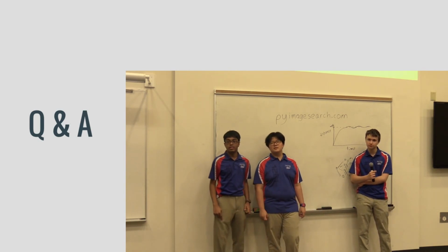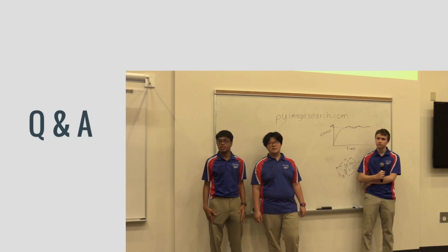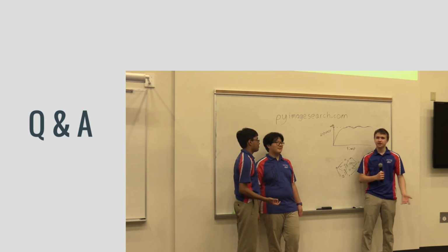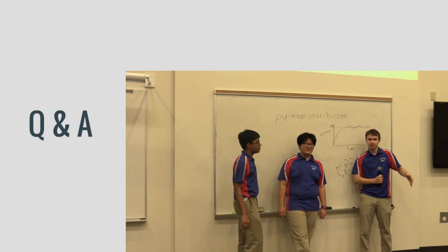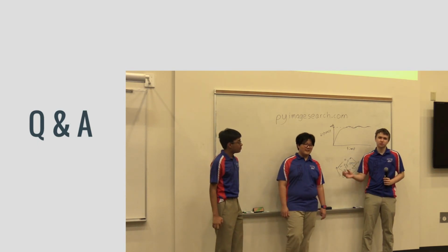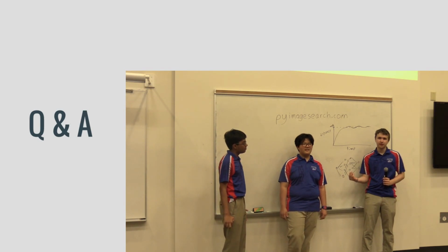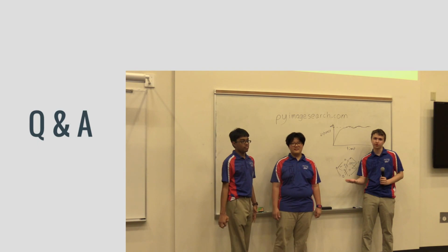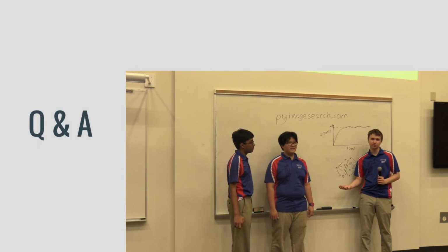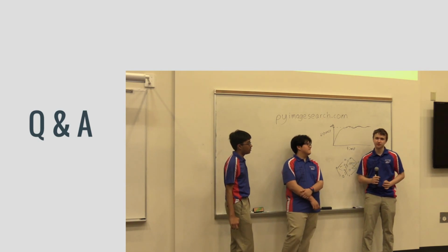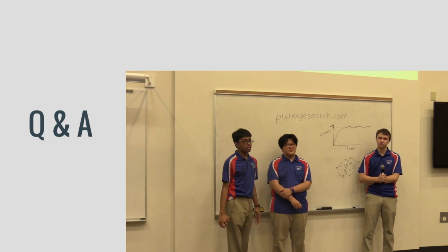How did you calculate the angle for your turning? Were you just counting pixels in your field of view? Basically, yes. We made the pixels into an unofficial unit of measurement for the robot. It literally just receives an offset, and it sees that number, and as it turns, it knows that number gets smaller, and it keeps turning until that number is small enough. So we are literally just counting pixels in the code, because it would be really inconvenient to try and convert into an actual unit.